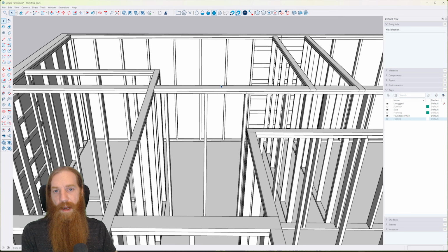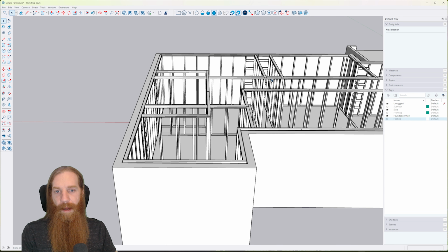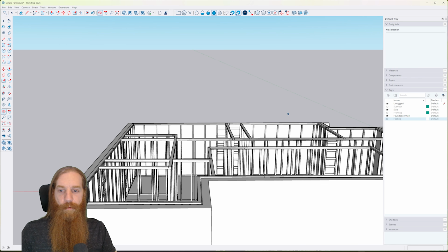Whereas when we're building the top floor, the main floor, there will be nothing locked in. See, in this case, the concrete locks in the joists, right? And so if we're nailing into the joists, all these walls will be locked in anyways. When we're doing the main floor, there will be no foundation wall, no concrete wall that holds the trusses in place. So even though the main floor wall framing will be nailed into the bottom of the trusses, those trusses rely on those walls being structurally sound in order for the roof to stay in place, right? For the trusses to be structurally sound.